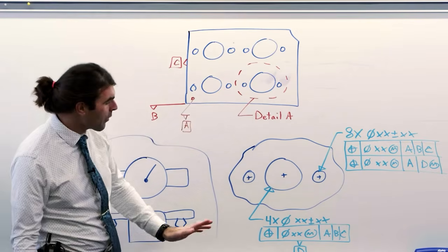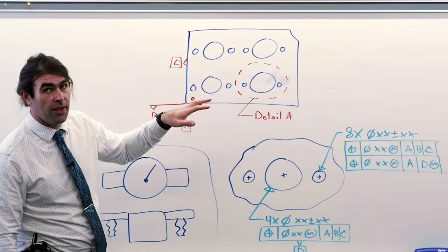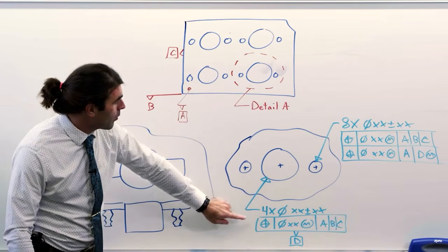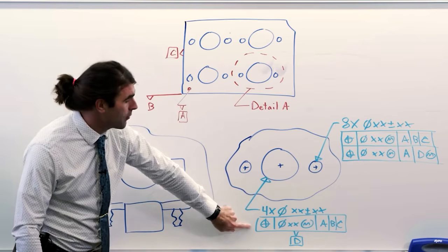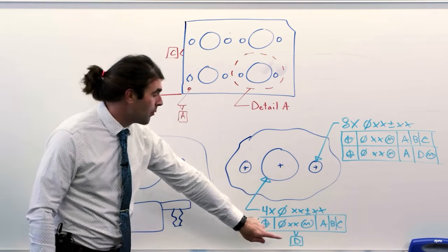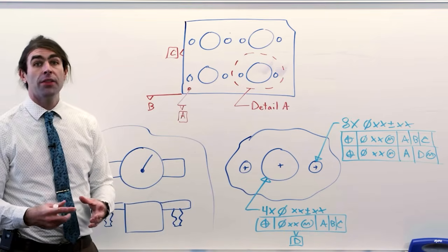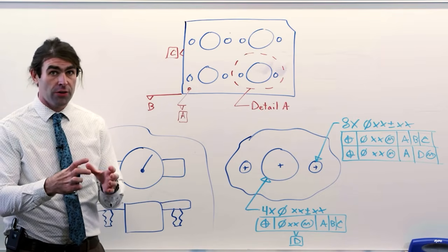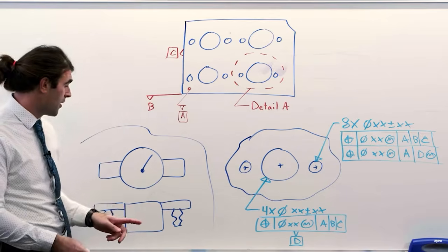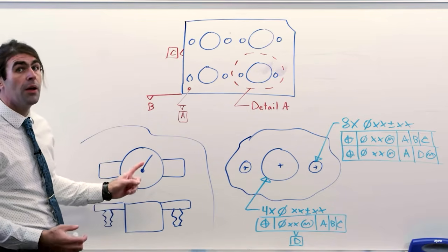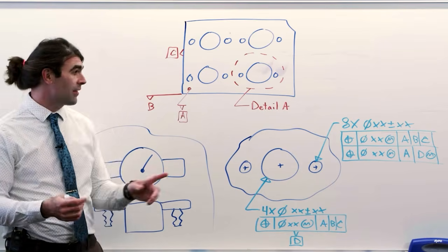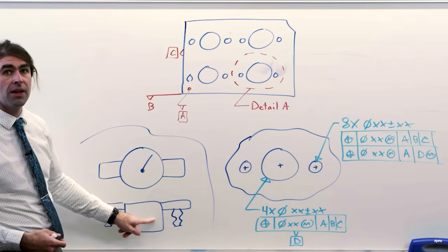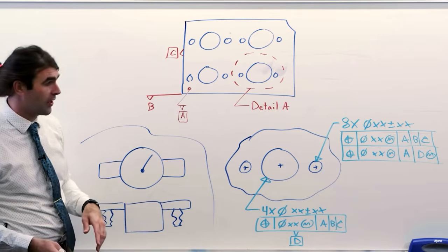All right, so how we're going to accomplish this, I omitted the basic dimensions, but they would come from the datums as they should. Here's a detail view. We're going to identify these 4 big holes as positioned to A, B, and C, and we're going to make that datum D. Now this can be a pretty loose tolerance, right? We're just controlling where the big holes are. As far as the location, they can be pretty far off and our instrument is still going to fit through there. But we couldn't apply that big tolerance to these little holes because if they're off, these studs won't fit through at the same time as the instrument itself and the other stud, okay?